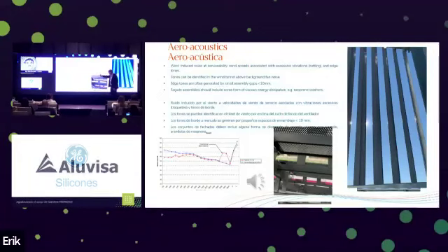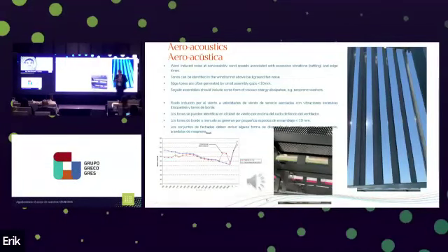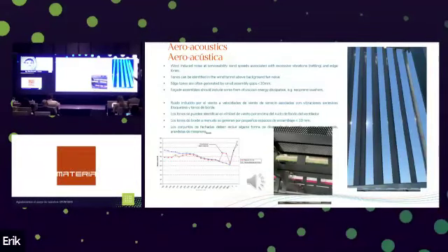Now, here's an example of a facade. I'll ask you to start in a moment, but we have a porous sheeting, but a very rigid assembly. No dissipation of energy available. All solid welds and tack screws, so there's no way for the energy to release. If you could start that.